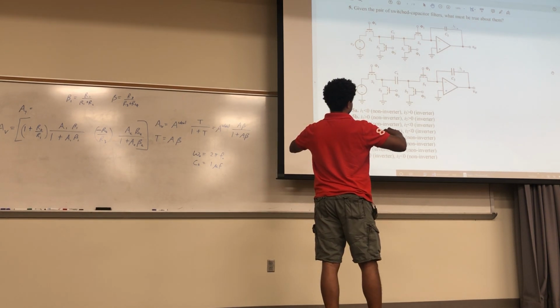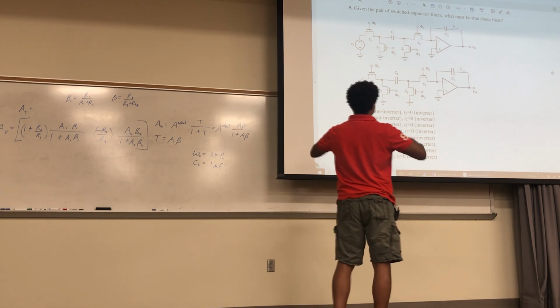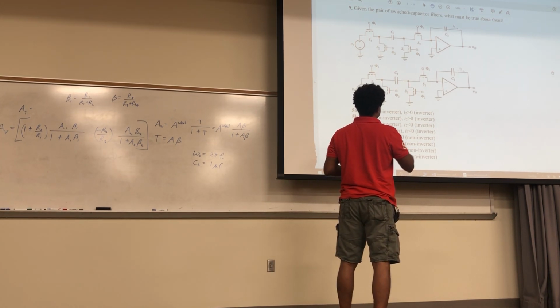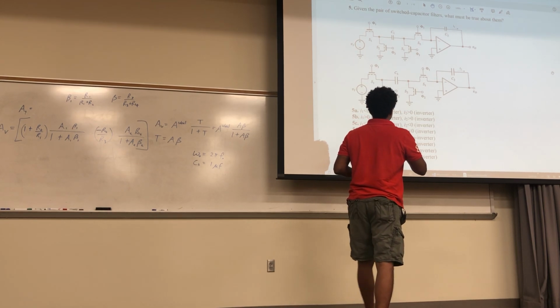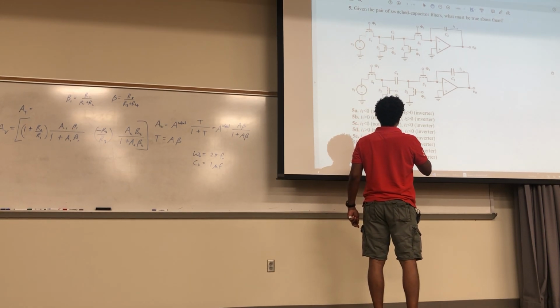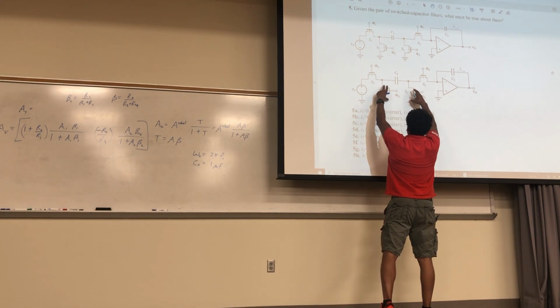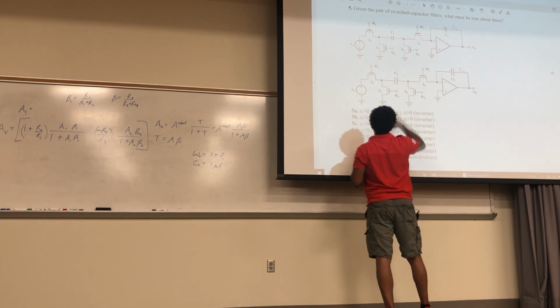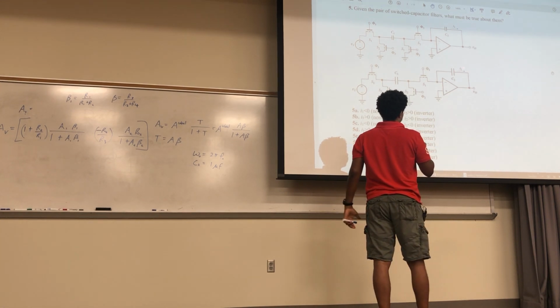And then you flip it where both of these are open and these are closed. So now you're going to ground and there's no path to go out of this. So once these are closed and going to ground, then any charge there just goes to ground. And then current stops.